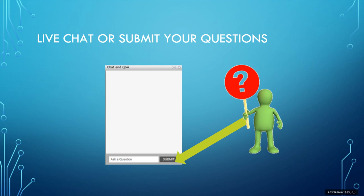On the oil-free compressors, which we now learned that they have as much oil in there as the other ones, it's a different story because you're using the oil pretty much for lubricating and sealing, meaning bearings and seals, and a little bit of the jacket cooling. So there, the challenges are a little bit different. Those compressors are running at much higher temperatures, so the stress on the oil is more or less the temperature and not so much the contaminants.